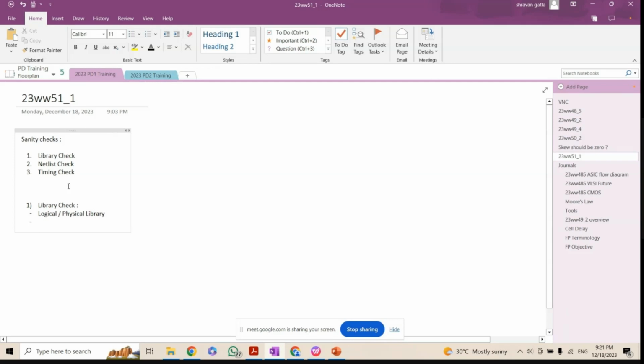Okay, if it is yes, then you will come here and arrange your macro placement and the module placement, everything here. Then again you will go to here and check the timing again. If you feel that timing is good, then it will go to the routing, and again they generate the steps, go to the STA, they check the timing. If it is good, okay, you're done with that.